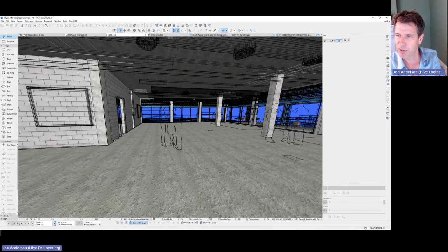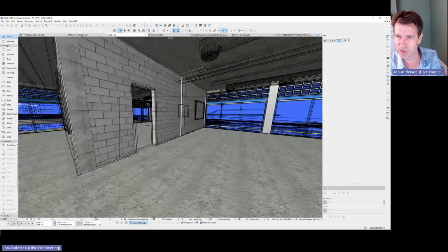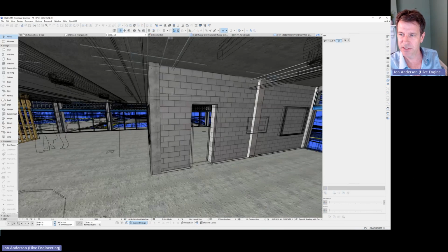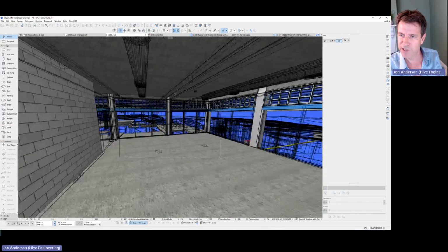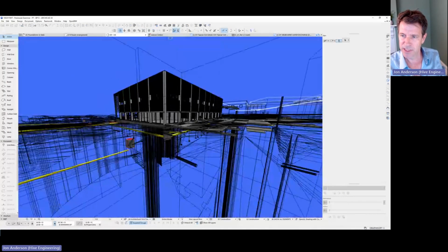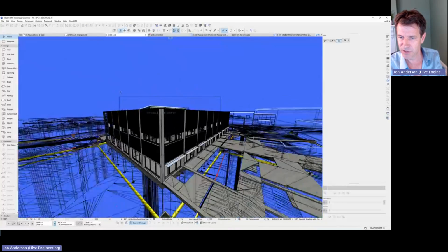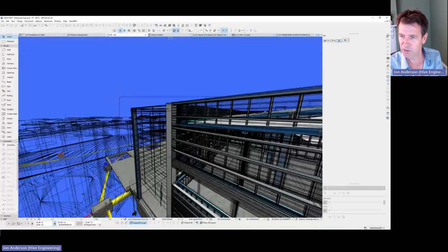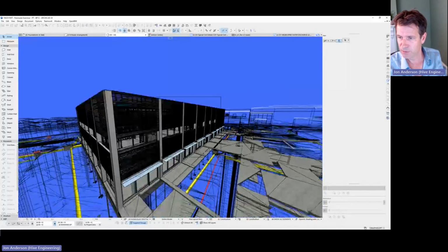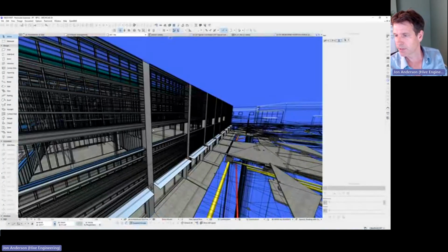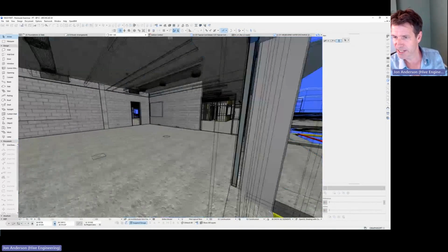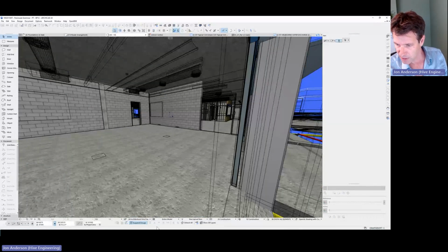Right, so this will give you a bit of an example. In the model I've got the architect's model here, and the structural model is modeled effectively inside it. So you can see the architect's model is in the wireframe. So as you model, you can align doors and that type of thing to the architect's model, and that makes it fairly efficient to do the modeling and make it accurate. And then all the 3D drainage elements are done in that as well.